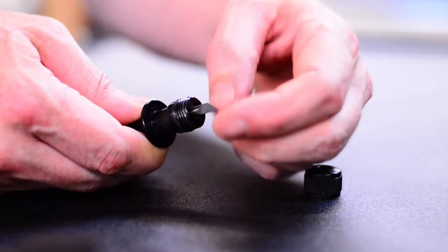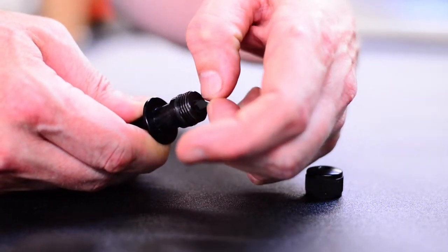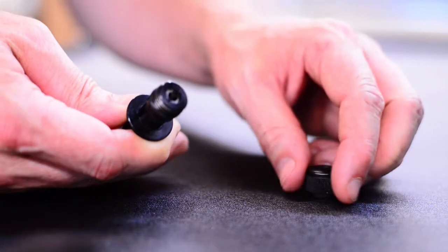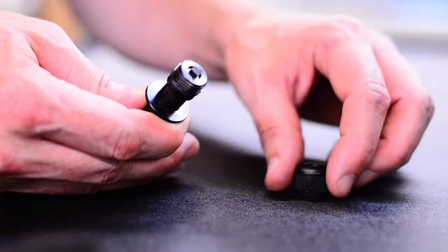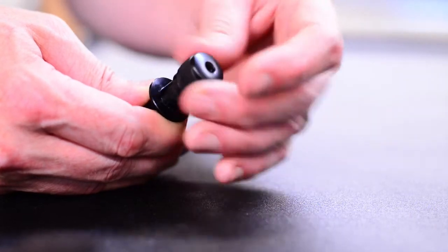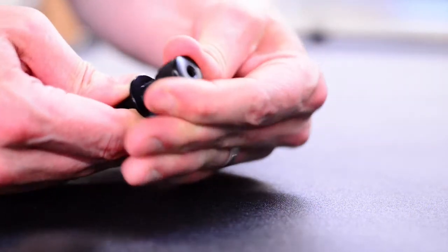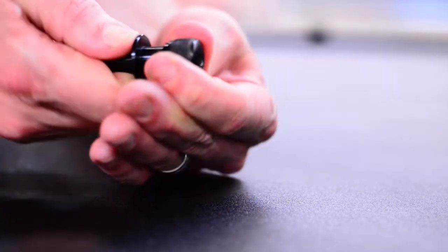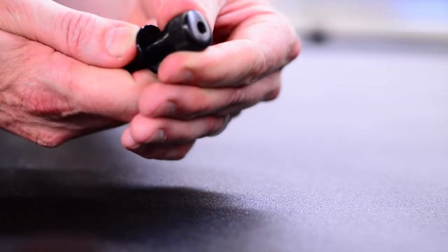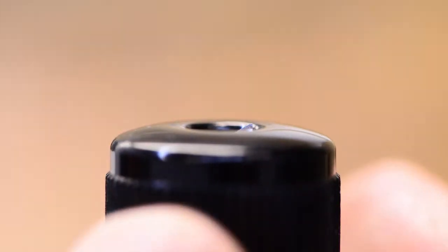Don't use metal or any kind of a surface to push that blade in. Just use your fingers, and then make sure the blade rotates properly with your finger. And then put the cap on, but don't tighten the cap. That's the important part. You want this cap to be on just enough to cut through one layer of twill at a time. So what we'll do is adjust it so that there's just a little bit of blade sticking out of the cap.